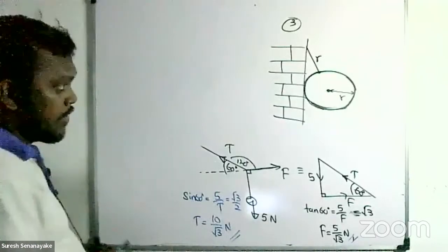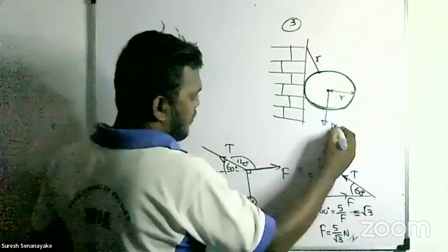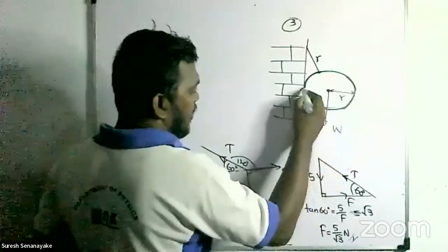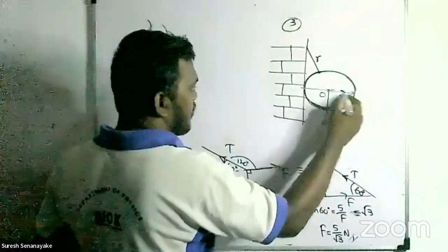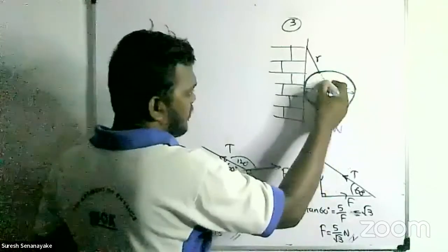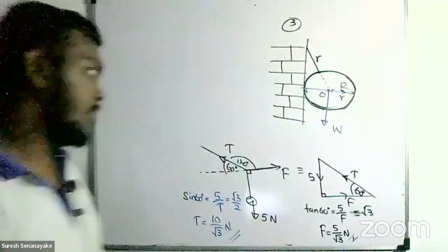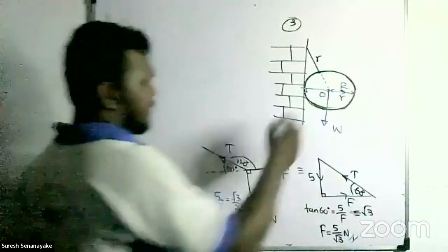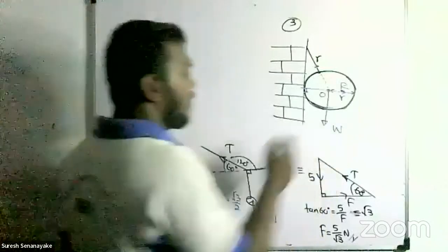Okay. And here, the forces are marked: mg, the weight, is given as W here. A normal reaction passes through the center of the sphere. This is perpendicular to the surface. This normal reaction, capital R, and the tension in the string should meet at one point, because in equilibrium only three forces are acting on this sphere: the tension of the string, the normal reaction, and the weight.